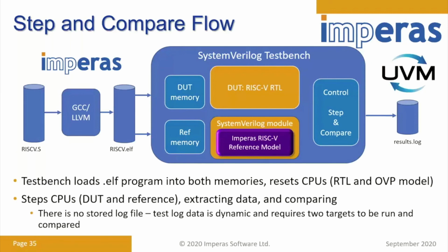So you have to consider things like, does your design handle misaligned load stores? Does it handle compressed instructions, so misaligned addresses for fetches, this kind of thing. You have to be aware of all these when configuring the device as your reference.